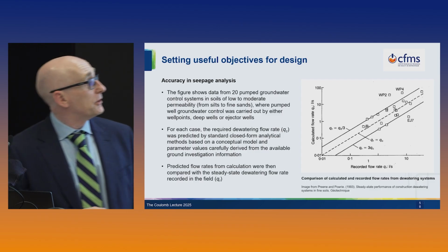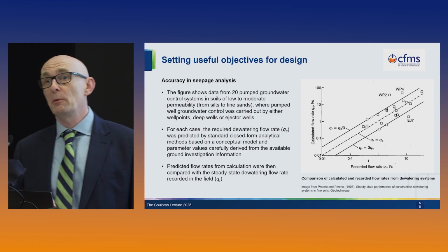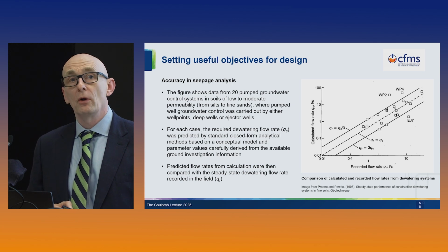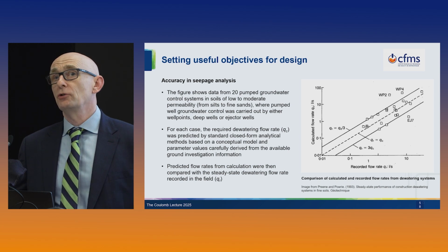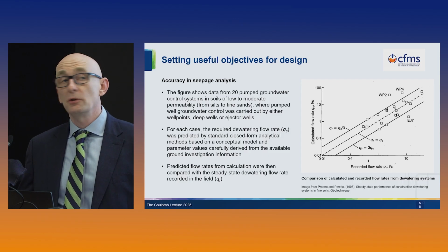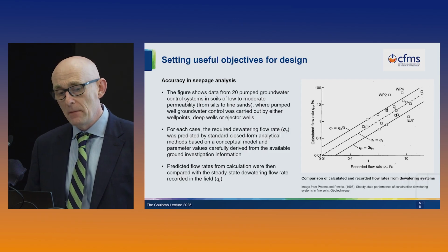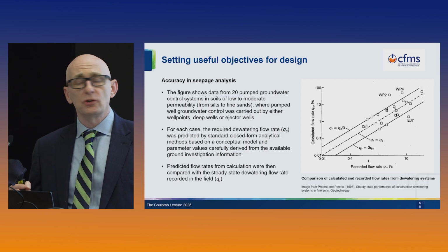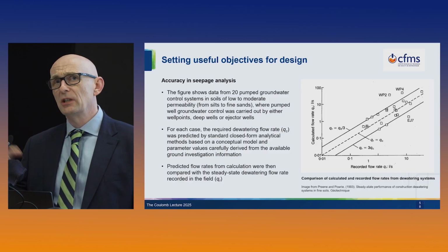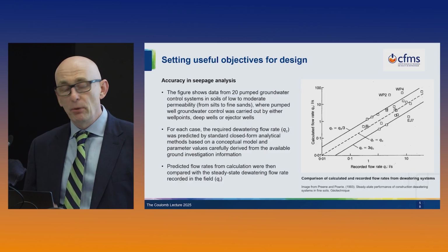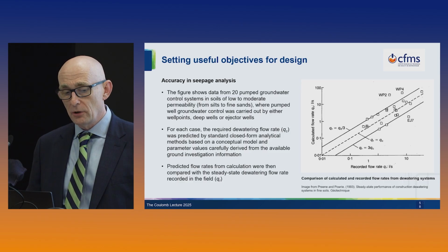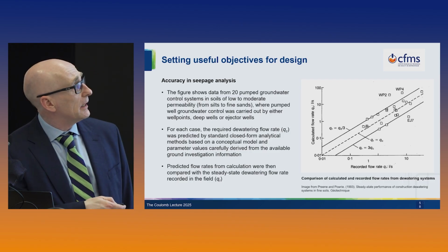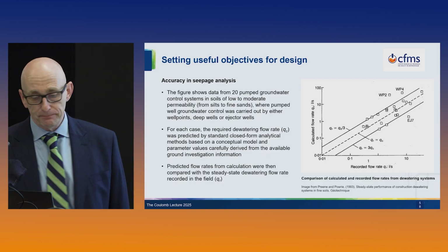So this diagram that I'll discuss in a minute is based on some work I did with Professor William Powrie more than 30 years ago, when we got 20 actual construction projects where ground control using pumped wells was being carried out. It was generally work in soils of low to moderate permeability, so silts and silty sands, and pumping was either by well points, deep wells, or ejector wells. And each dot on here is a particular project.